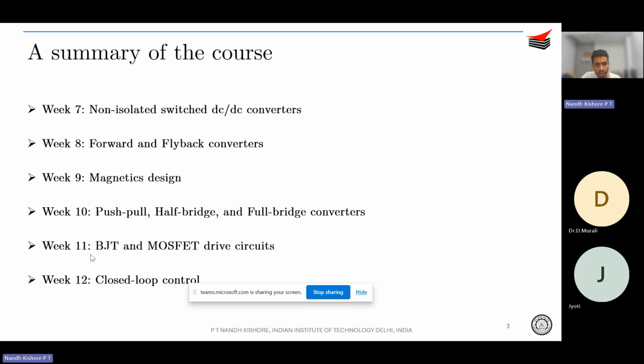That is, we model the entire converter in terms of its state space equations or the state equations. So we know that the converter is essentially made up of power devices and L, C, and R, right? In that case, we know that for the capacitor, the voltage is kind of stiff, and for the inductor, the current is kind of stiff. So if we can model how they are going to vary, then we can derive a mathematical model for the converter.